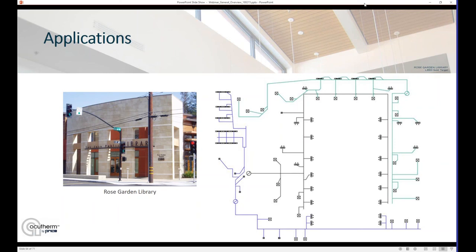When one of those zones needs heating, the whole zone can go into heating. That means you're really eliminating energy wastage from reheat, as well as reducing pressure drop in your system. This is an all low pressure design system, and then fan speed control to provide the pressure control into the system. And then those Therma-Fuser diffusers, sub-zoning each of those zones, providing that individual control throughout the space.